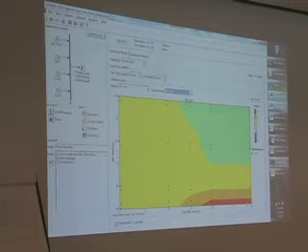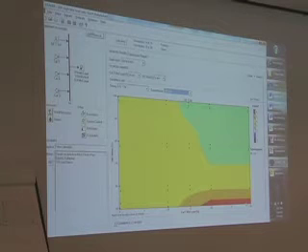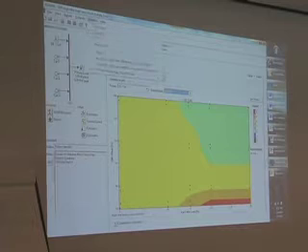minimum loading works, this issue about adding wind to the system, which is displacing diesel power, but you still need the diesel capacity for spinning reserve. There's a conflict there. And that's why things like flywheels and storage become really valuable as a way to provide that operating reserve without running your diesels at very low loads. So that was the example I wanted to show.